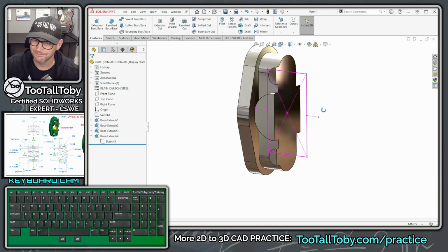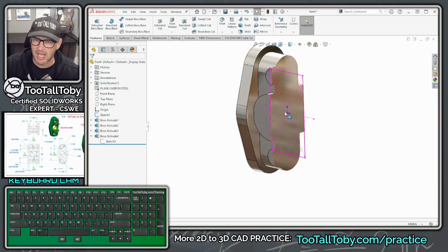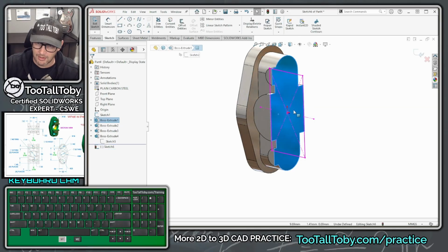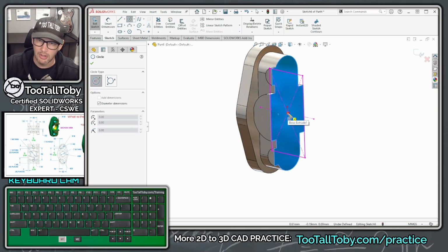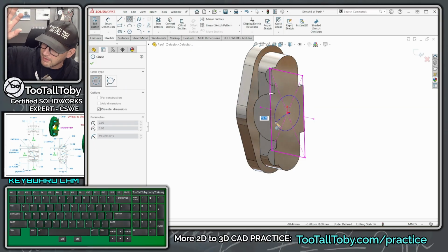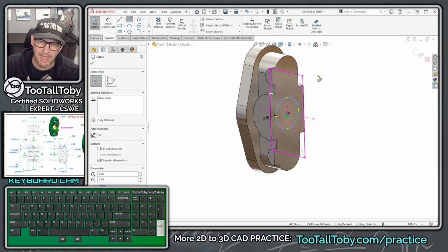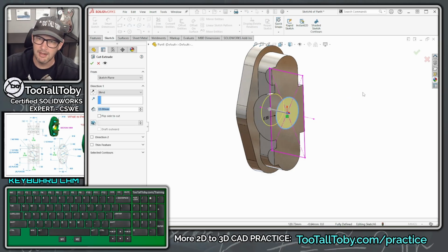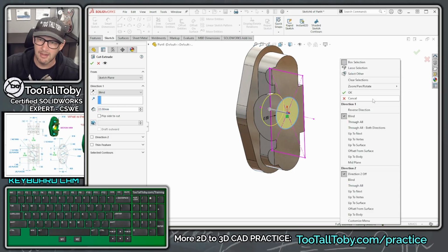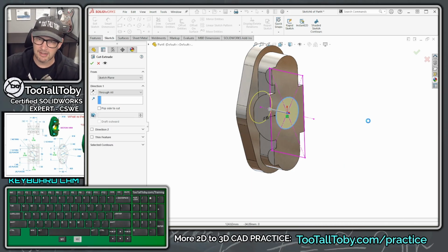We got it right. So create your solid geometry first, then go through and start punching your holes in your geometry, and you'll find yourself in a great spot. So to punch those holes in the geometry, we'll start out here on the right plane, S key, create a circle right here at the origin, move our mouse, let go of our mouse. We're going to type in a diameter there of 35, enter, S key, extrude cut, move your mouse a little bit, right click, come down here to through all, left click, and then immediately right click again.